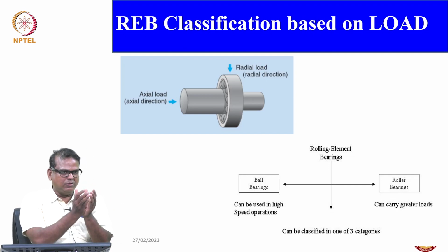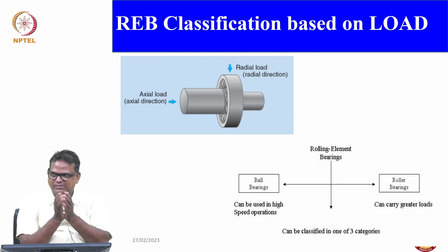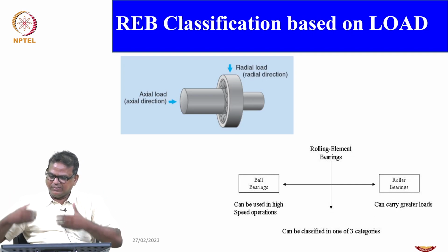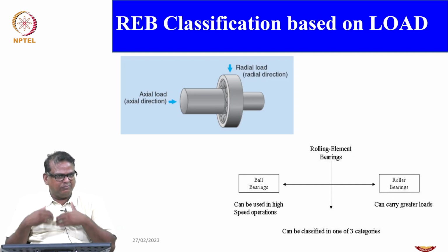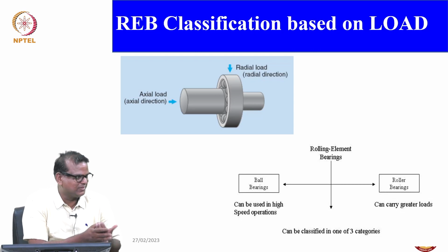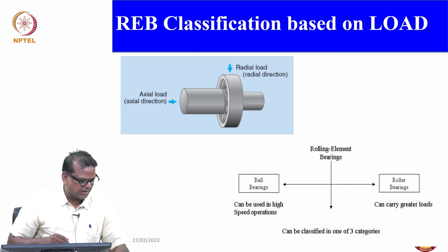So, for the same load, in point configuration the load will be very heavy, whereas it is uniformly distributed over the line. That is why the roller bearing, which has line contact, can withstand more weight compared to ball bearings. Okay. That is information, and I have some samples.